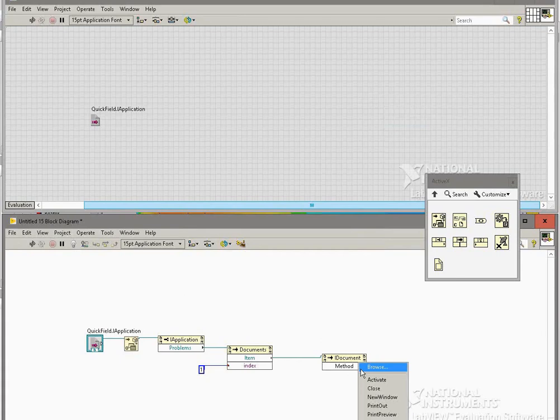When we get the item from the collection, we get in fact 2 objects. Here we see the methods of the iDocument object. iDocument could be a geometry model file or physical properties data file. So I can only close the window or save the file. To get specific iProblem object properties, we should perform object type conversion. Use the variant to data block.